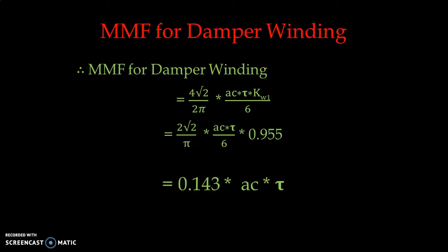So our first step is over. The first step is very critical to calculate the exact magnetomotive force to be generated by the damper bar, and the function of the damper bar, as we have discussed, is to suppress the inverse rotating field. So how much magnetomotive force is to be generated by the damper bar is very important.